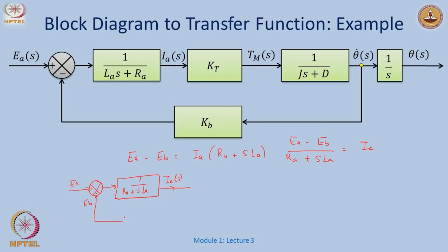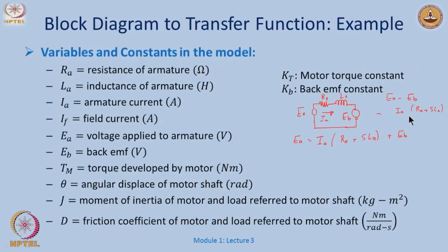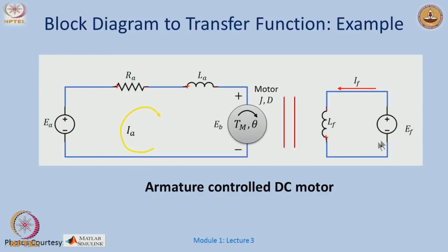Okay. So, what do we know in a motor? The torque is proportional to the field current and the armature current. The basics of a DC motor teach this. But here my field is constant, it is a separately excited machine. If you see this picture here, E F is constant. So, the torque as a result of this would have a constant effect.